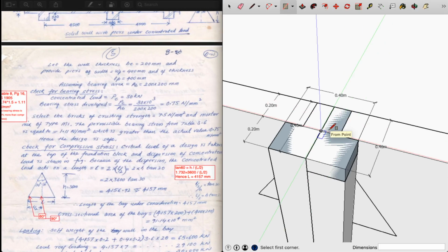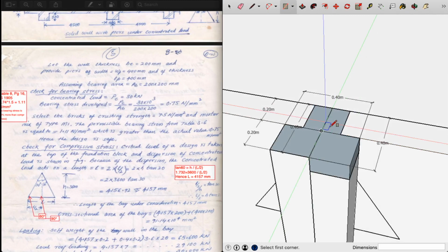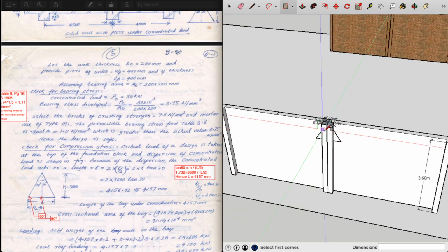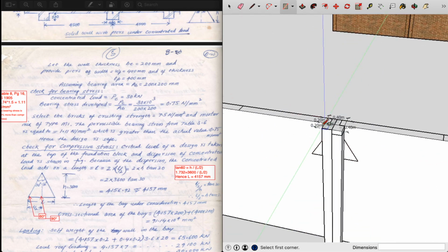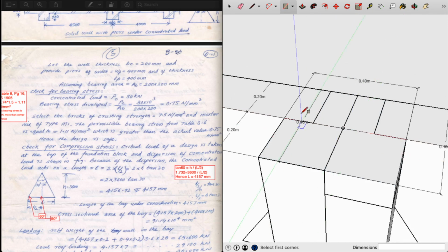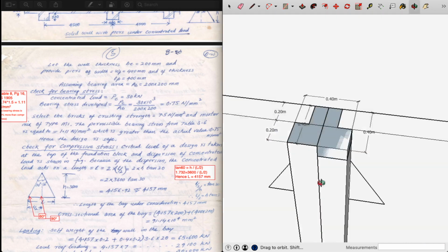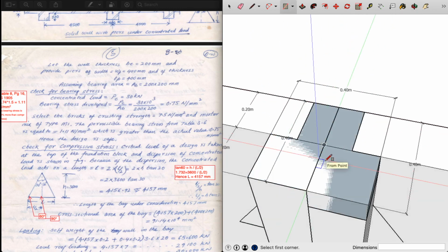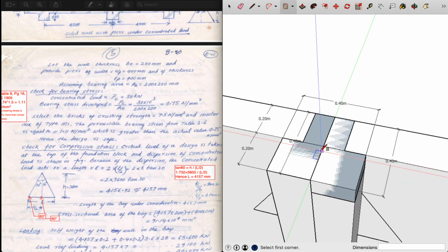So there is a clause where the resistance offered by this particular brick unit at this particular area is actually much higher compared to the crushing strength offered by the entire wall unit. That increment in strength is attributed either to lateral restrainment or to the triangular distribution of load, but the increment is in the magnitude of 50% more than the basic compressive stress obtained from table 8.